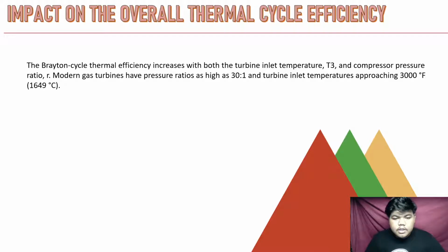And for next, I will brief a bit about thermal cycle efficiency. Modern combined cycle gas turbine (CCGT) plants, in which the thermodynamic cycle consists of two power plant cycles, for example the Brayton cycle and Rankine cycle, can achieve a thermal efficiency of around 55%, in contrast to a single cycle steam power plant, which is limited to efficiencies of around 35 to 45%.